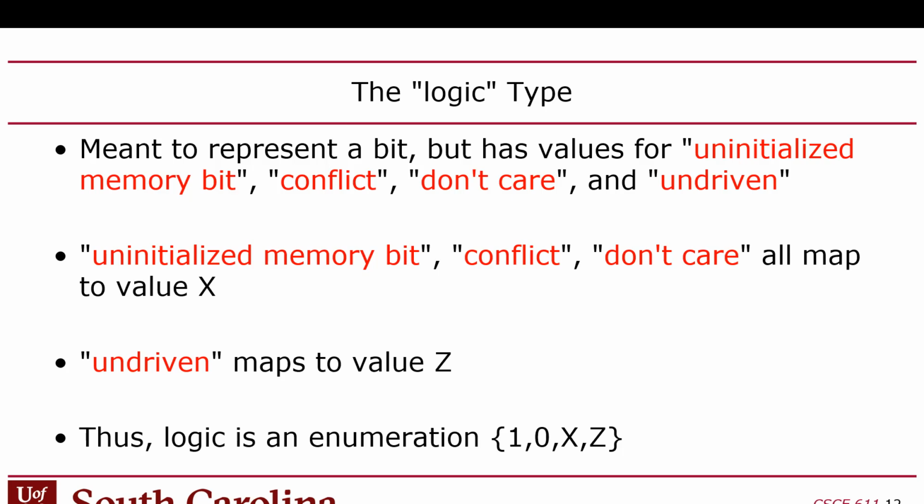But when you simulate HDL, if you don't initialize memory, in the simulator it needs to come up as uninitialized, because when you design the HDL, you're designing a generic digital logic circuit, so you can't assume anything about the memory. So there's a special value for that. In Verilog, it's X. In VHDL, it's U. But it's not 1 or 0.